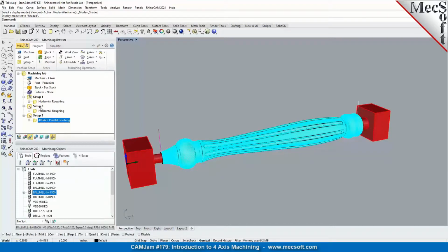Having said that, the other thing that Uday showed was the combination of both indexed and continuous finishing. What I would like to say is, when you are removing large amounts of material, like in roughing or even in pre-finishing, if you're leaving stock and you're removing material, it would be preferable to use the index machining methods, because you're locking the table, and that would give you more rigidity in the machine. So as far as the machining characteristics are concerned, it would be better to do it that way.